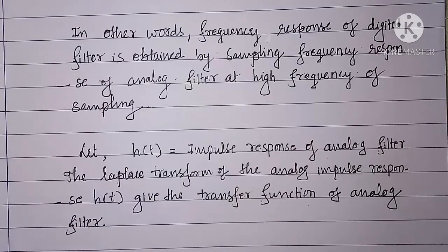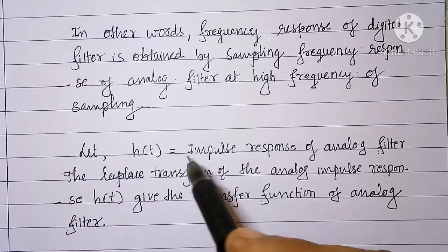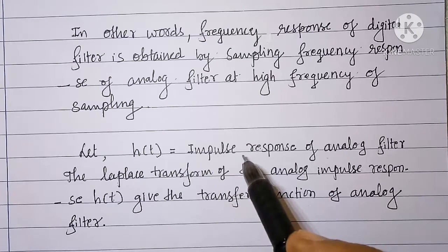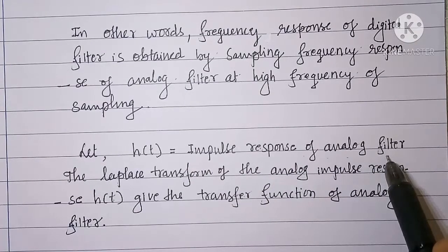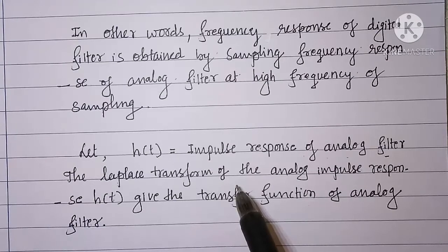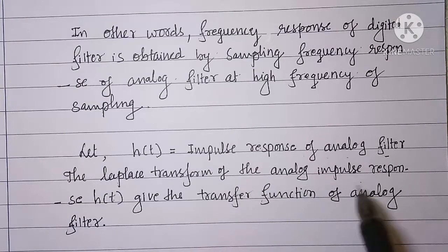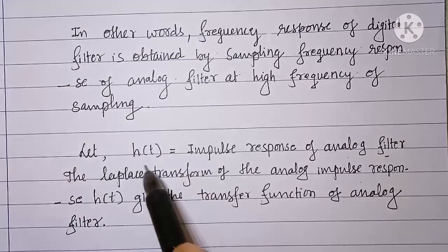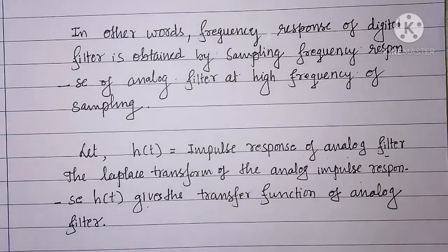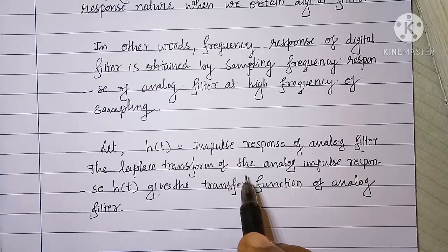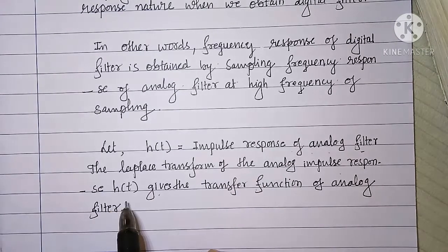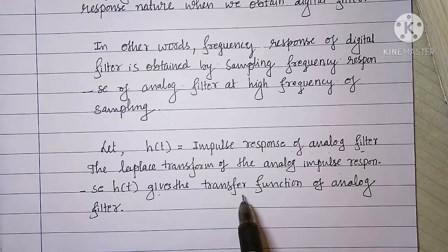Now let us understand the impulse invariant transformation technique. For that, let us consider h of t as an impulse response of analog filter. The Laplace transform of the analog impulse response h of t gives the transfer function of analog filter.